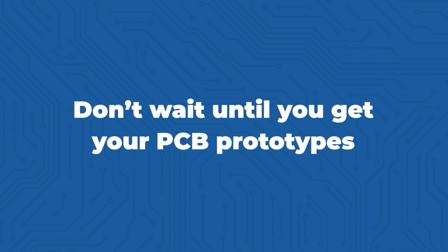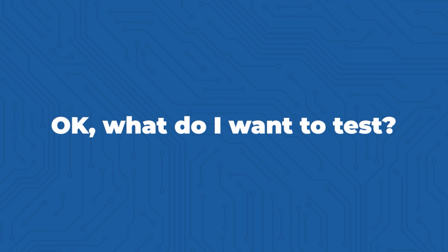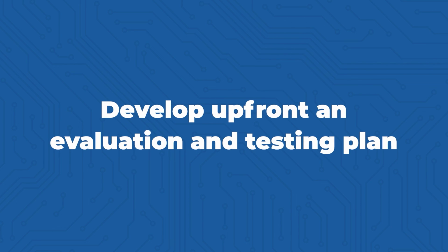One thing that can be really helpful is, don't wait until you get your PCB prototypes, you have them on your desk, and then you begin thinking about, okay, what do I want to test other than the most basic function? Beforehand, before you even get your prototypes back, it's really wise if you could take the time to come up with a test and evaluation plan.